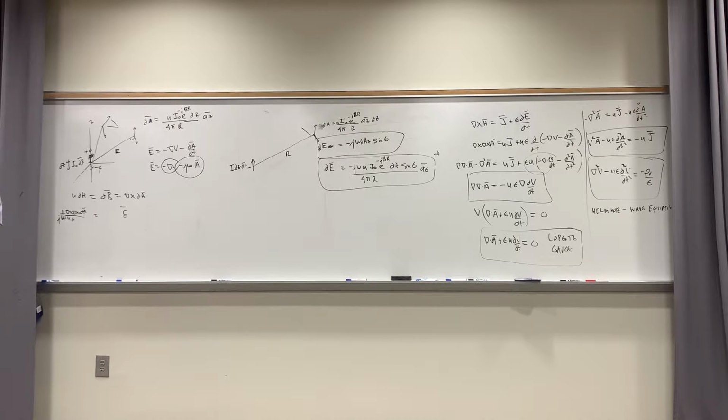That energy is resident. If you have an inductor, a bunch of coils of wire with a current flowing in there, there's magnetic energy in the near field, causing a magnetic field, right? The magnetic energy density is 1/2 mu H squared per volume, in joules per meter cubed. And it's about there. But if you have that much current going through an inductor and put a resistor right on the ends of the inductor, all that magnetic energy would be deposited in the resistor. Do you follow me?